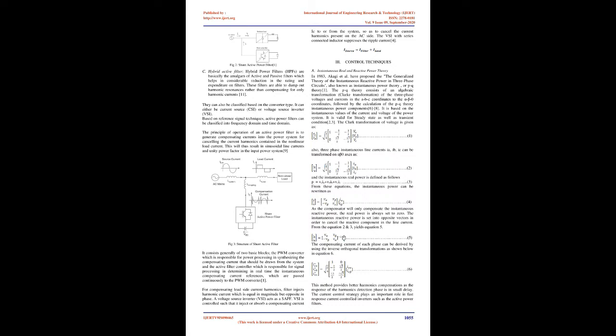Active power filters, APFs, are a solution to overcome the disadvantage of passive ones. APFs can adapt itself to any load change. The shunt active filter have been researched and developed that they have gradually been recognized as a feasible solution to the problems created by nonlinear loads. They are used to eliminate the unwanted harmonics and compensate the fundamental reactive component consumed by the nonlinear loads through injecting the compensation currents into the AC lines.